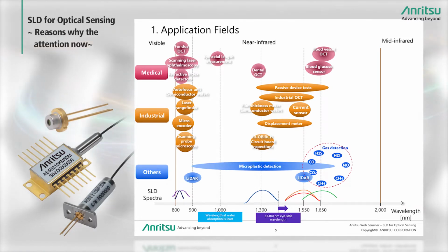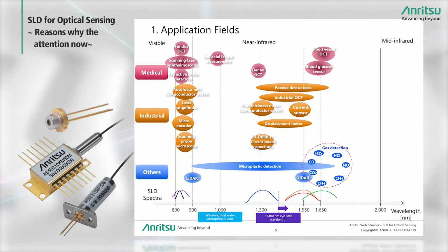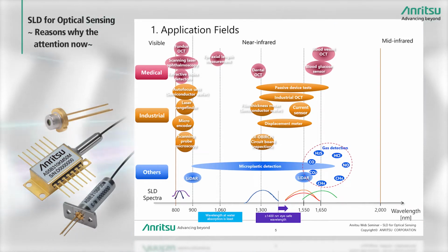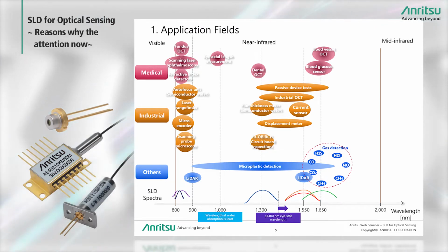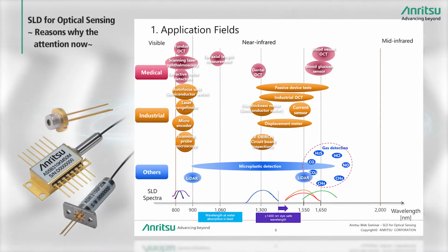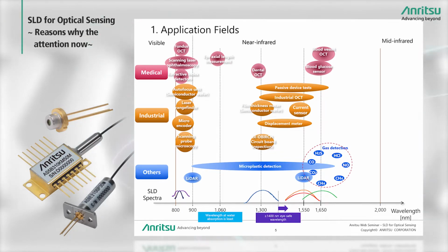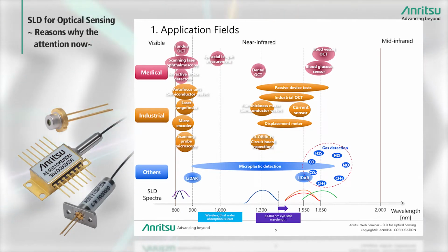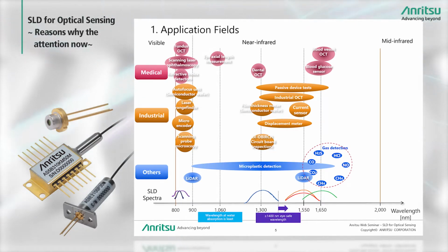In particular, wavelengths of 1400 nanometers and more are described as eye-safe, so LiDAR automobile applications commonly use wavelengths of 1550 nanometers. Moreover, wavelengths between 1500 and 1700 nanometers have good absorption characteristics for different gas species, so they are used by gas sensing detectors.